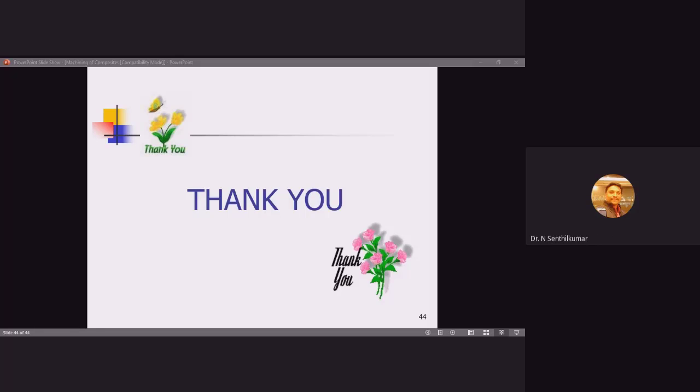Normally we will be going with the relief angle, sir, because on the rake angle only the chip will be sliding over the rake face. The relief angle and side cutting edge angle will be in contact with the workpiece. If I provide some relief, only the cutting edge will be in contact with the workpiece. But providing over-relief will reduce the strength of the cutting edge and it will be easily chipped out. So a maximum of 3 degrees will be good for you to have as a relief angle.